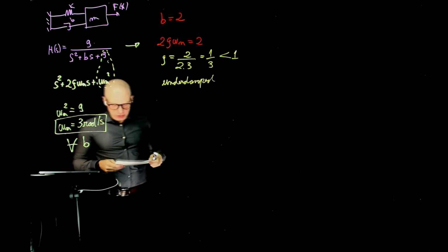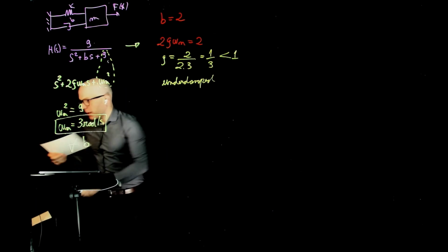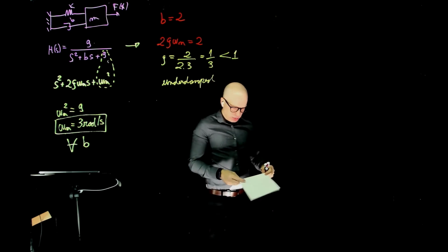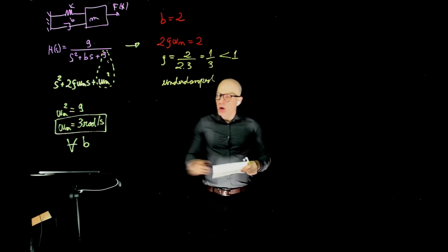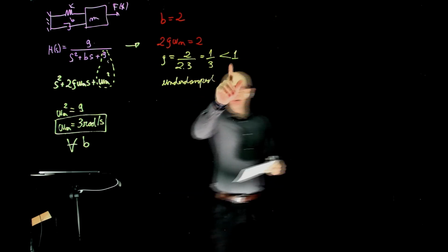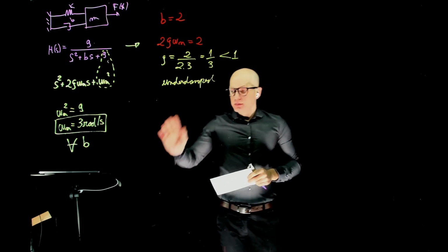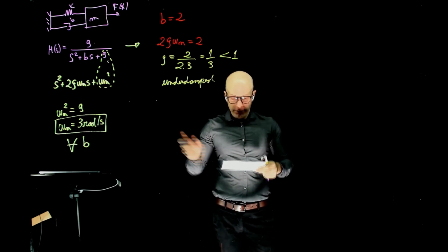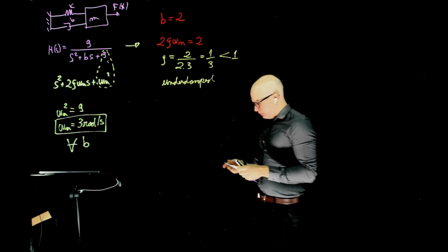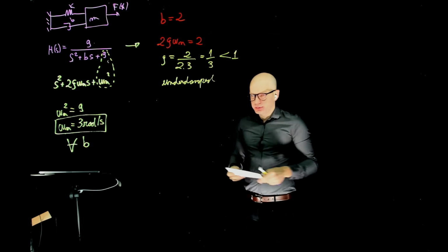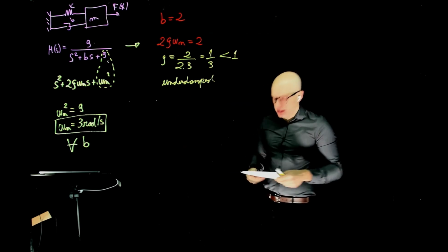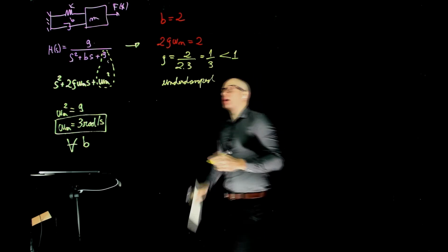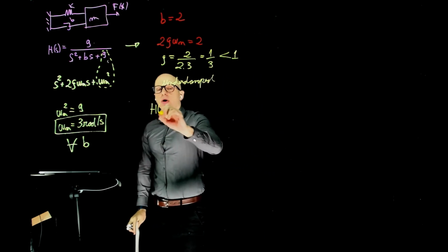What kind of temporal response do we expect from this? A converging exponential and sinusoidal. Correct. And why is that converging? Because this is less than 1, and the real part of the poles is positive or negative? Negative, right? The poles sit on the left side of the S-plane. Okay, so this means that we now have complex conjugate roots.